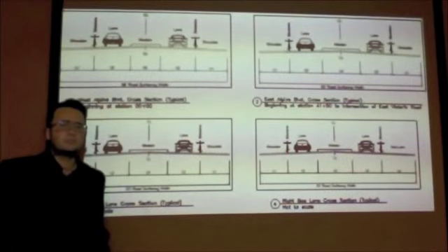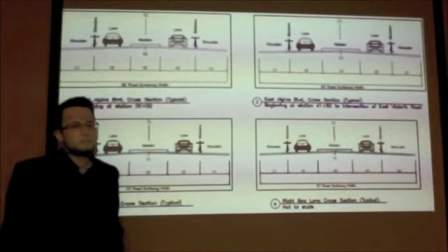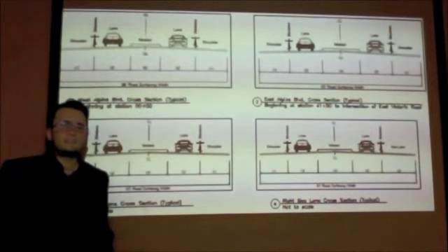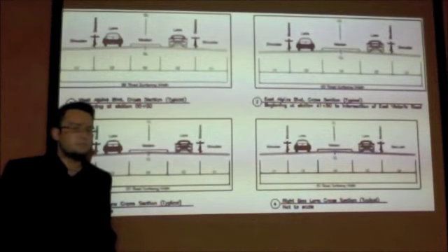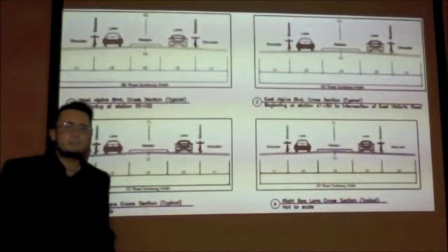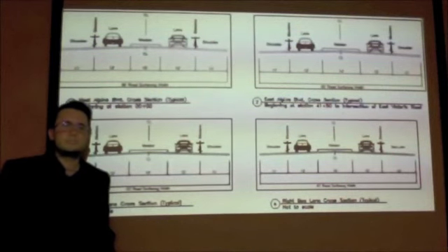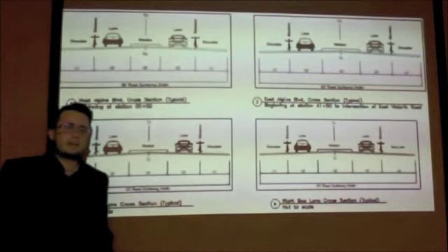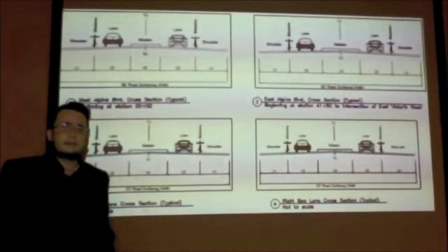Typically, the majority of boulevards carry heavy traffic, such as buses and trucks, and this is not the case for this particular project, since the traffic on Alpine Boulevard is formed mostly by residents and neighbors. The engineers in charge decided to use a specialized material which would extend pavement design life, rubberized asphalt concrete, because of its resistance to cracking and aging.